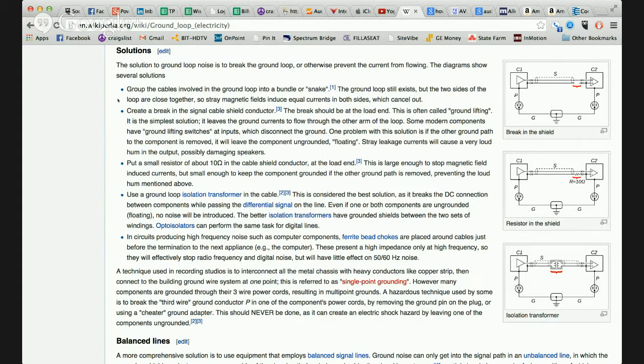And you need to do whatever you can to eliminate all EMI from getting into your sound system wherever you can. This is why you don't run them parallel, because, again, without getting too technical, you're just inviting EMI to